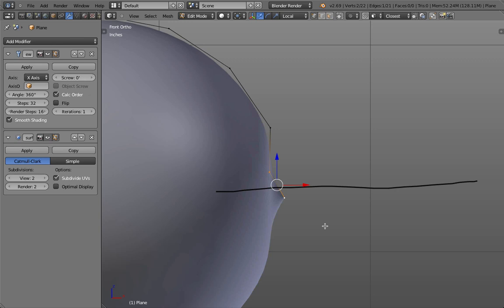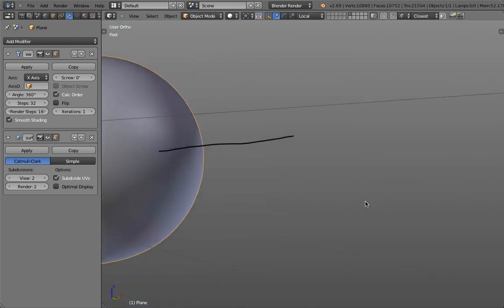So two ways how I can do it. I select both, Shift S, X, and 0, or I turn on vertex snap, click on the X arrow, and then Control, remove my left mouse button, and it snaps. I can move this one down if I want to work a little bit with the flat part.